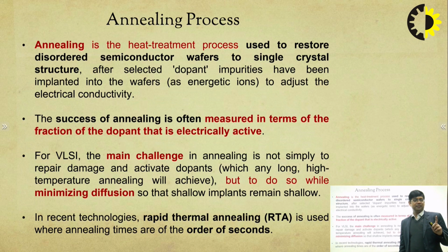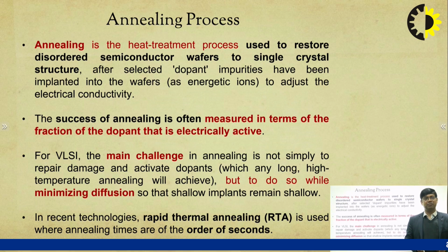And the success of annealing is often measured in terms of the fraction of dopant that is electrically active. It is not the case that all the dopant atoms we have introduced into the wafer are electrically active. Until they come to the substitutional sites and make a proper covalent bond with the host silicon atoms in their surroundings, they are not electrically active and they are not functional.